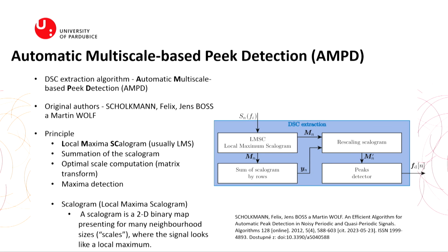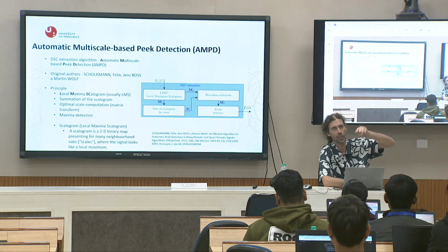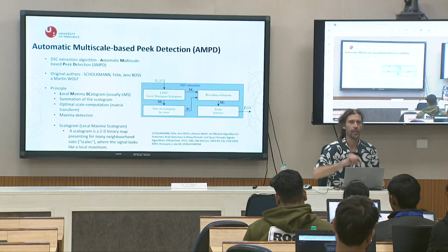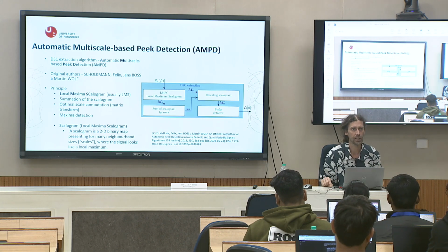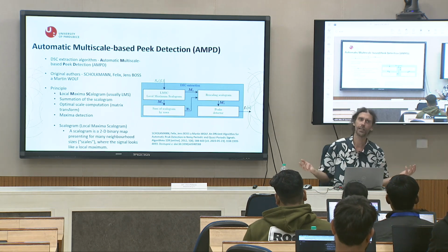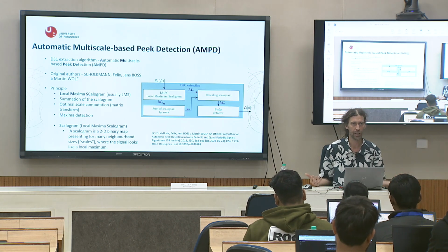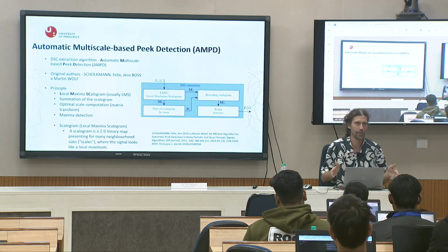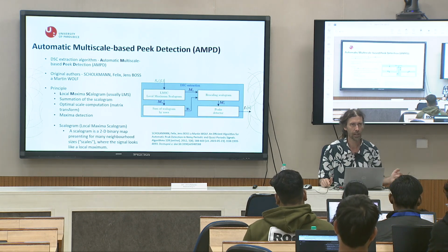After this we make a summation across rows, and this gives us a vector whose largest values correspond to robust peaks. So exactly where you have this jittering and some maxima, it will locate these maxima even with this jittering. It will be highly dependent on noise. If your amount of noise increases, then clearly you can hardly recognize this quasi-periodic or periodic behavior, and then it fails.